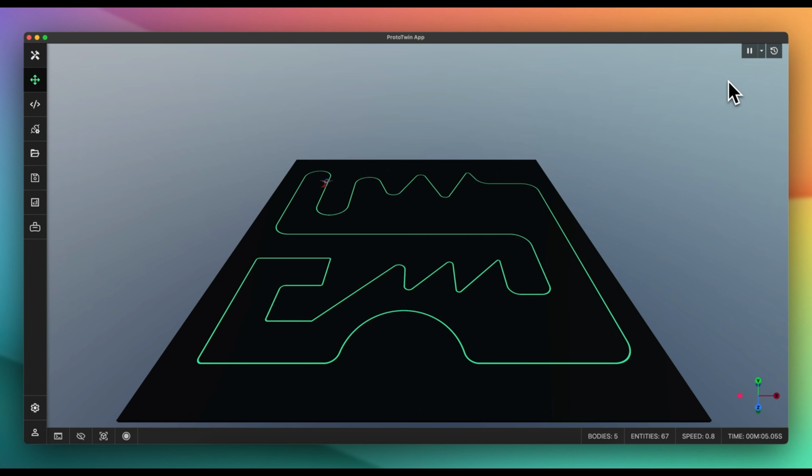Every time step, our script is reading the state of each color sensor, determining the current value based on this state, then evaluating the PID controller and using the control value to determine the speed of each wheel. For such a simple script, the robot moves remarkably well around the sharp corners of the track.